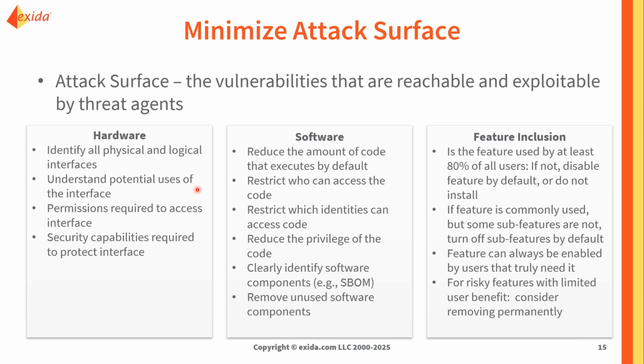If you have one interface for a service connection, that will have higher levels of access than, say, one interface that's just used to provide information to an HMI. So we want to limit exactly what you can access from each interface to the minimum amount required for its function. Additionally, we can think about, well, what permissions are required to access those different types of interfaces, and how do we make sure that the security capabilities for that interface match its use.